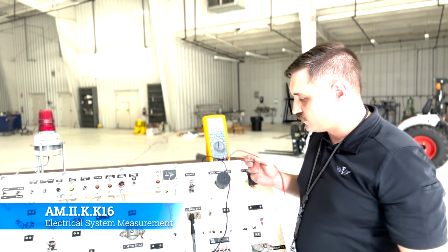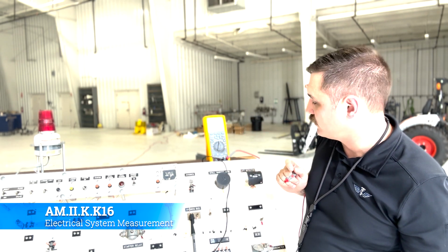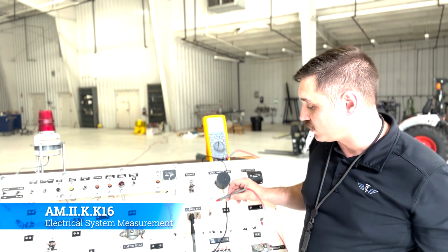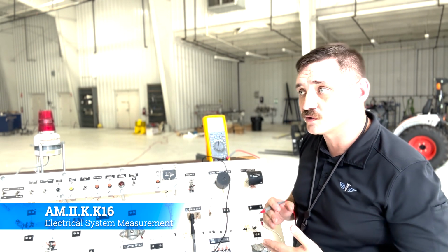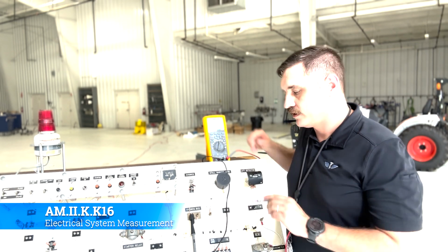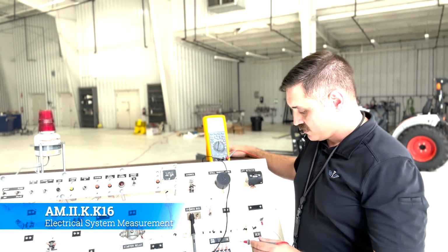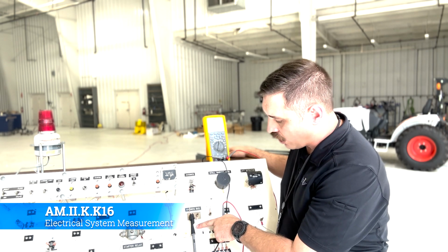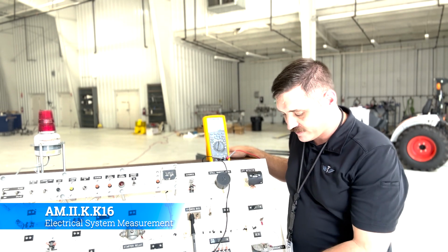All right, so we're set to mega ohms. We have continuity, or we have ohms selected. We have the auditory alarm on. We're going to check it, so we know that our meter works, and that's something you always want to do: always make sure that your meter works before you get going, or else you might end up accumulating a lot of data on a system that really just says, hey, your meter's broken. And then, look, we have a wire number here that says R3B20. That's Romeo 3 Bravo 20. So we're going to go down here to our avionics relay. Let's see if we can adjust a little bit.